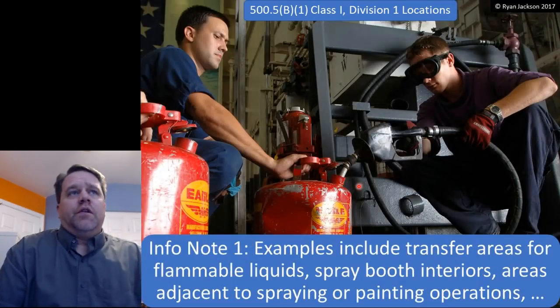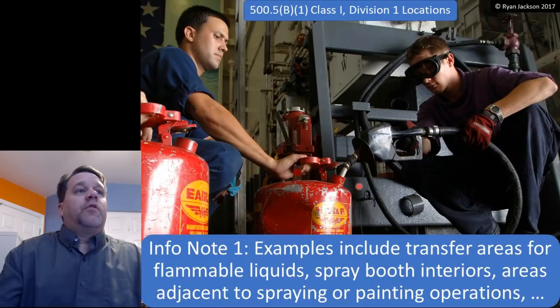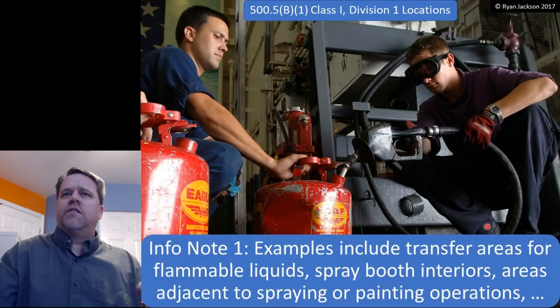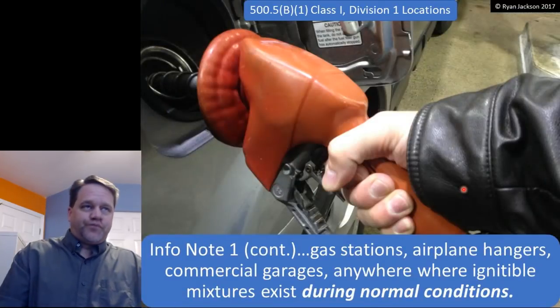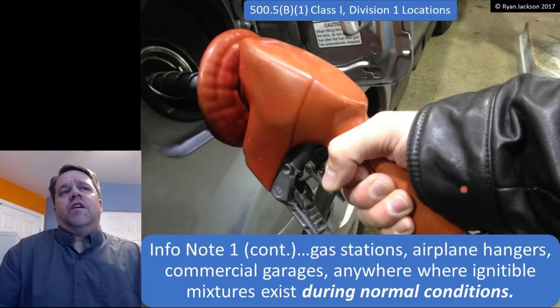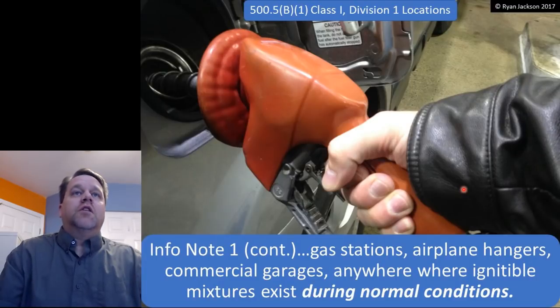There's an informational note saying examples include transfer areas for flammable liquids, spray booth interiors, areas adjacent to spraying or painting operations, right? So here we're doing what? We're transferring a flammable liquid, right? Gasoline has a flash point that's less than 100 degrees F. It's negative 36 to negative 50, so that's a flammable liquid. This is a transfer area for a flammable liquid. That's a Class 1 Division 1 location. Gas stations, airplane hangars, commercial garages, anywhere where ignitable mixtures exist during normal conditions. That's a Class 1 Division 1 location.